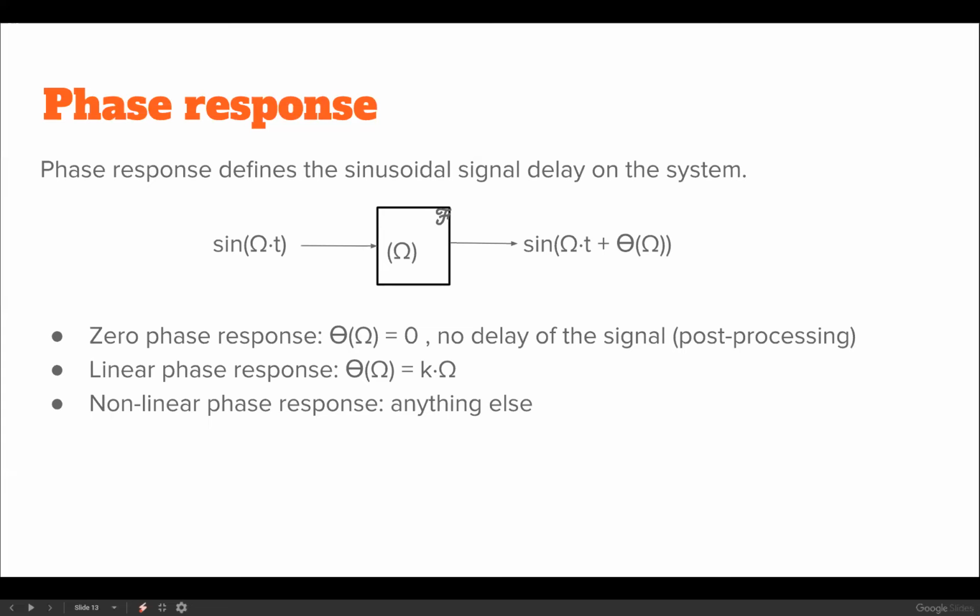It can be done in the digital domain if you do post-processing of signals. In the analog world, you cannot do a zero phase response system. Well, actually you can, if it has only resistors, but those are not really interesting systems at all. If you add any inductors or capacitors, it immediately means that you would have a nonlinear phase response. That's how nature works.